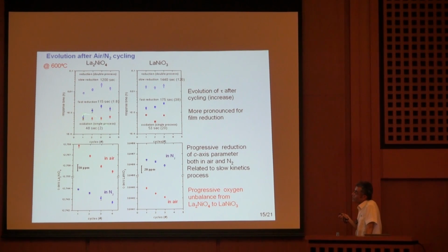And in this case, we observed that the oxidation surface exchange rate, or time response for the oxygen incorporation, is more or less the same for both materials. So it means that once the oxygen incorporates into the top layer, it is immediately felt by the bottom layer. So the oxygen crosses without problems to the bottom layer, which means that there is no diffusion problem at the solid-solid interface, which is interesting because it's very difficult to measure by other techniques.